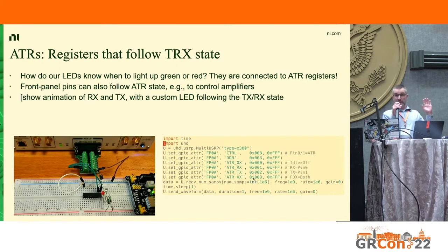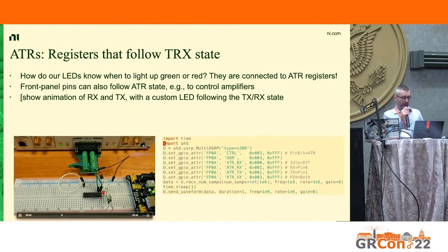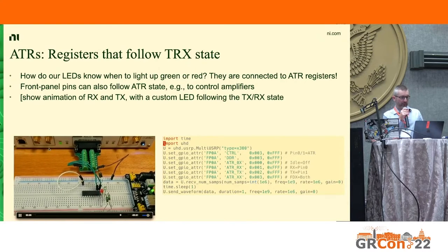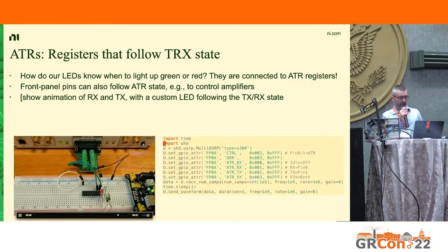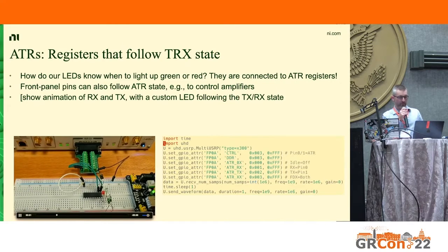And then we step away and say, now go. In this script, we're going to do a receive for 1 second, and a send for 1 second to see if that works. You can follow the LEDs here next to the SMAs to make sure those are the ones that we're trying to mimic. And I put this on a loop. So, when we receive here, this LED will also turn on. When we transmit, you can see it here, this LED will also turn on. That's how you do that.